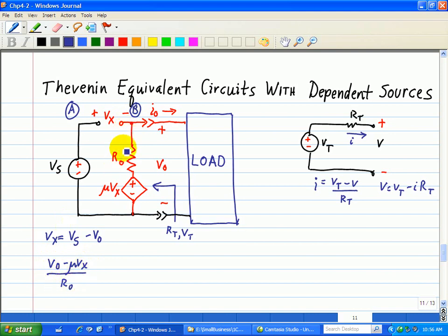That's basically the voltage difference across RO, and using Ohm's law, we divide by RO. That's the current. So the current's leaving; there's no incoming current going into node B. And so what's leaving is the current through RO, as I described here, plus IO is equal to 0.